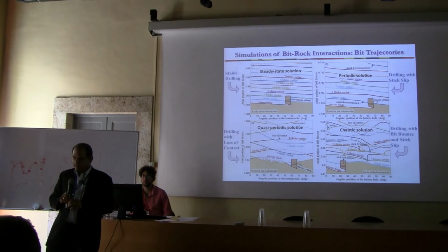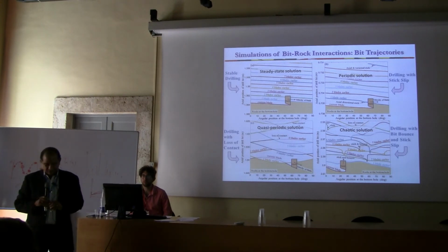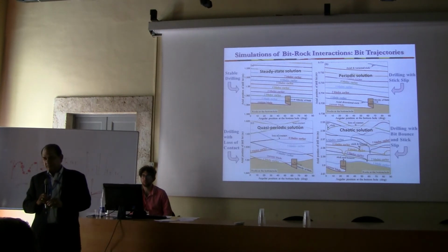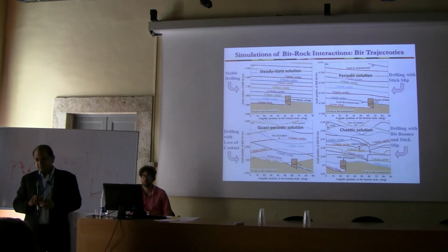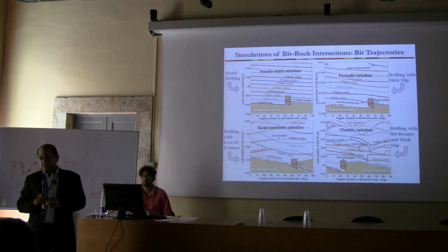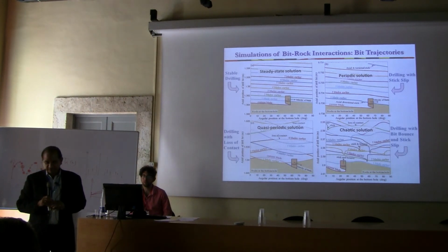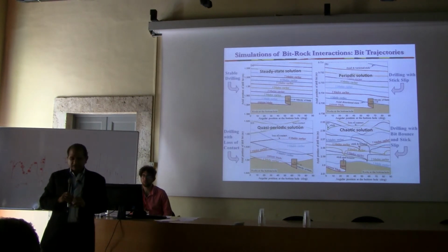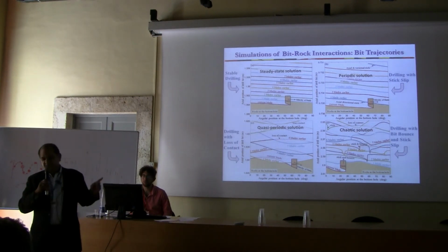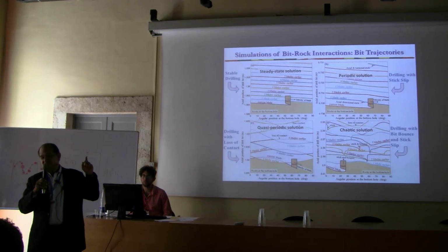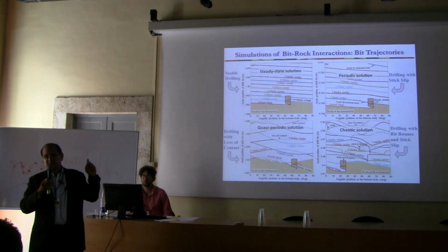Because some of the work that we have done uses Hertz's law for the nonlinearity that you are going to have when the drill string hits the wall. I am not sure that I show it in the analysis. So I think we didn't take lateral dynamics into account in this study. We focused on axial and torsion dynamics.